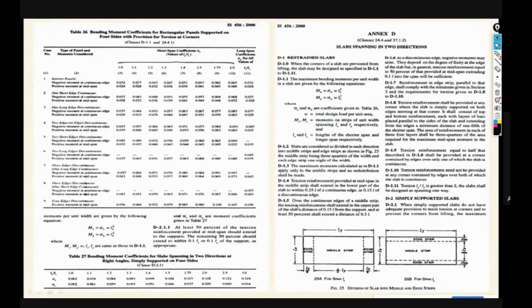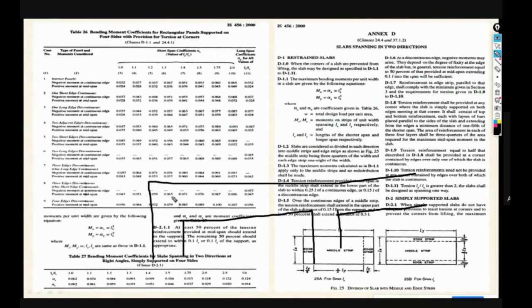Yes, in the continuous slab. Now see, in beams also we are doing this. If you see the detailing of a beam, let's say this is our continuous beam. Suppose this is our middle support. In this also we are providing extra top reinforcement. If you see the previous design, about five to six years before, we were providing bent-up bars in the beam, correct?